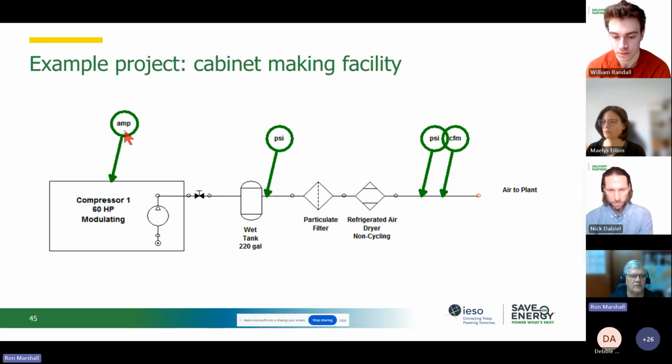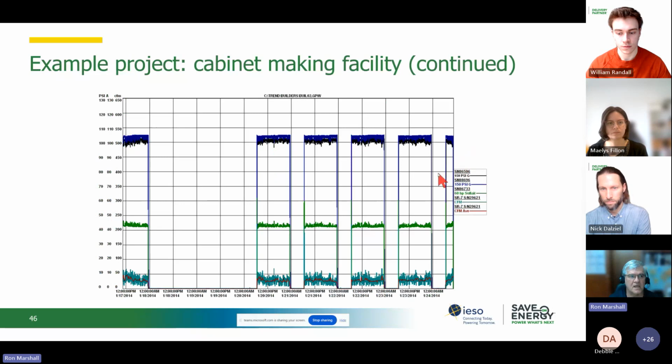So we measure the amps, and we measure pressure across the cleanup equipment. We want to see what the pressure differential is. And we're lucky enough in this tiny little place to have a flow meter, which makes it a lot easier to calculate what savings would be.